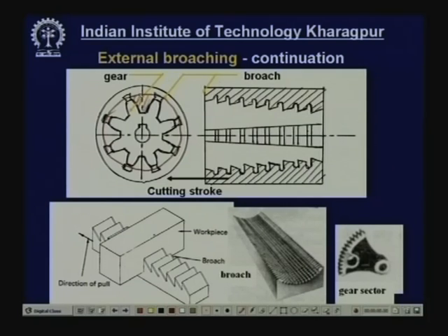How can you do it? By shaping it is possible by a number of passes, but if you take a strip type broach, this one, when this will be pulled through this piece, then this groove will be made. If one groove can be made, why not this groove also? So, this strip will make this one. If two, then why not this one and this one?